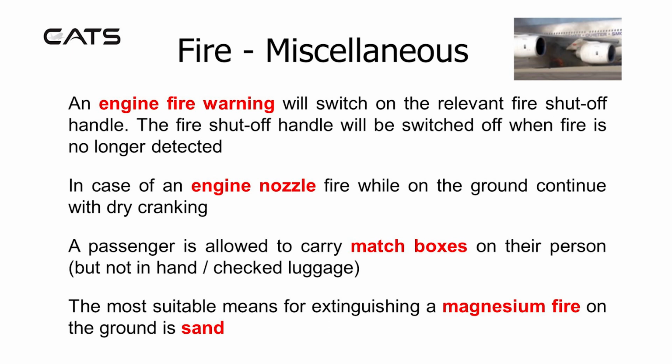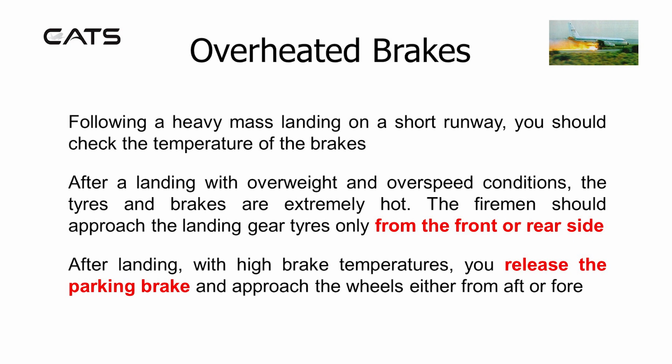In the case of an engine nozzle fire, while on the ground, continue with dry cranking. A passenger is allowed to carry matchboxes on their person, but not in their hand or checked luggage. The most suitable means for extinguishing a magnesium fire on the ground is with sand. Overheated brakes. Following a heavy mass landing on a short runway, you should check the temperature of the brakes. After landing with overweight and overspeed conditions, the tyres and brakes are extremely hot.